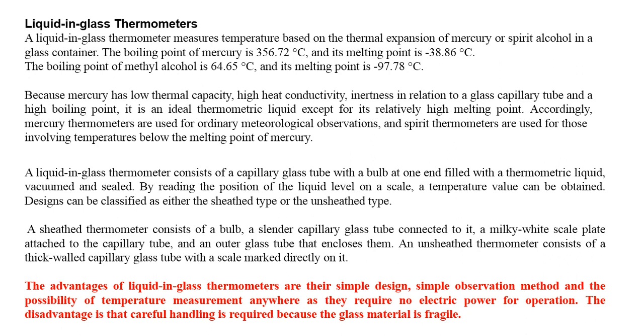Now, the advantages of glass liquid thermometers are their simple design, simple observation method, and the possibility of temperature measurement anywhere, as they require no electrical power for operation. The disadvantage is that careful handling is required because the glass material is quite fragile.